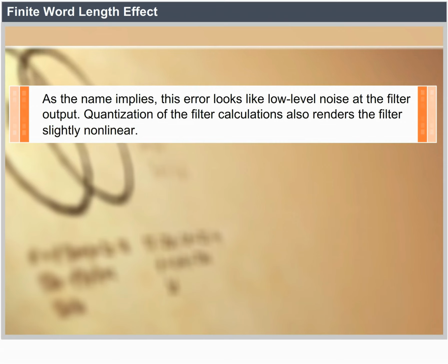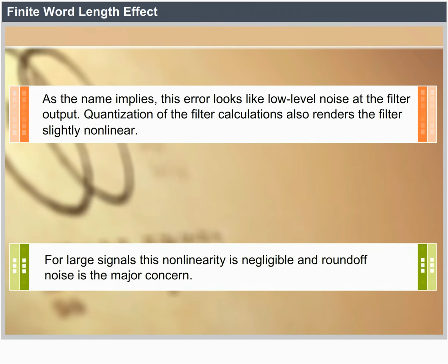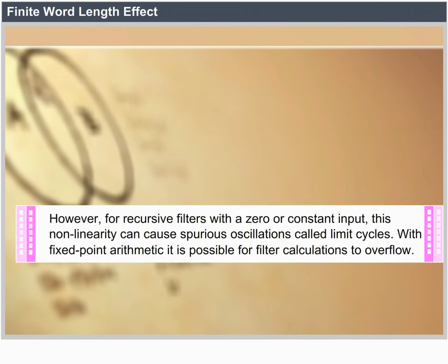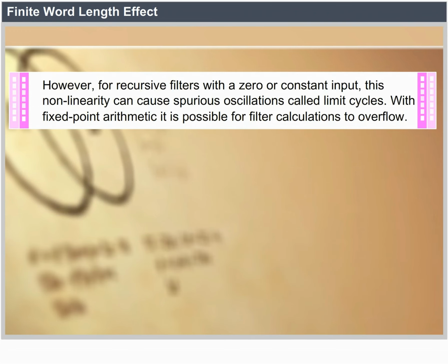Quantization of the filter calculations also renders the filter slightly nonlinear. For large signals, this nonlinearity is negligible and round-off noise is the major concern. However, for recursive filters with a zero or constant input, this nonlinearity can cause spurious oscillations called limit cycles.